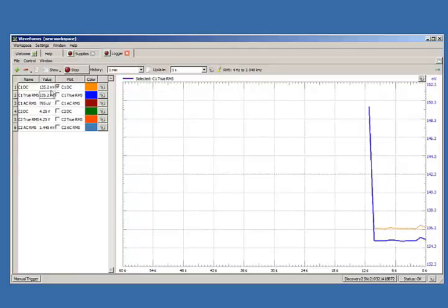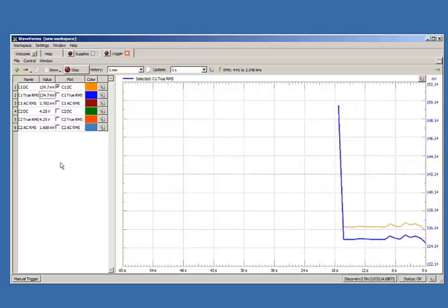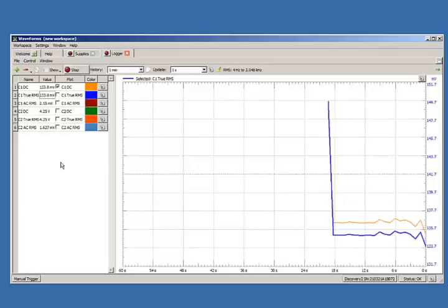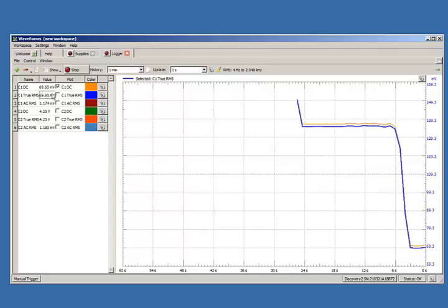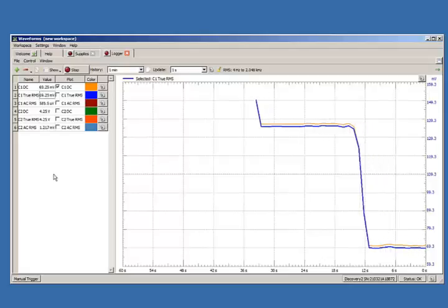At the current position of my platform, I have about 135 millivolts of output voltage. I'm going to move the platform down by about 10 inches. That'll give me a new value for this. The difference between those two values divided by the distance that I move it is going to be my sensitivity in volts per inch. So record those two values, do the math, and you're done with this part.